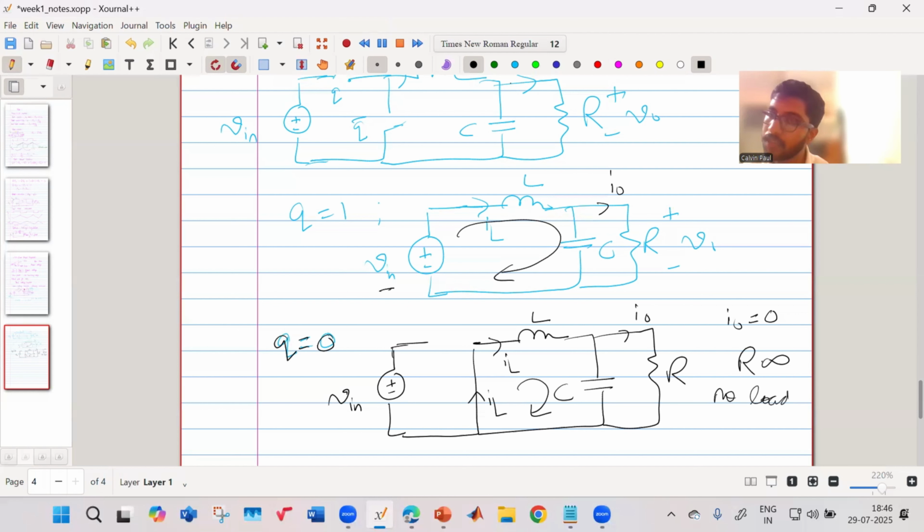You will see that even in a buck boost converter. So in all these boost derived converters, for some time you have to store energy in the inductor, and then transfer the energy to the output. That is why it is indirect energy transfer. But in a buck converter, the input voltage energy is directly transferred to the output when you connect it. That is why it is direct energy transfer.